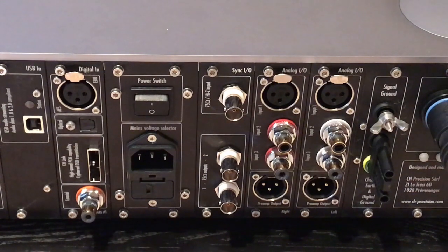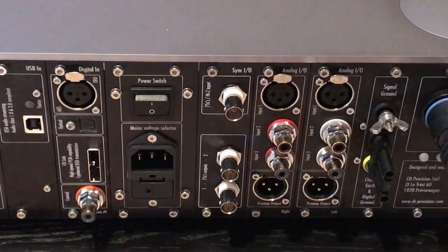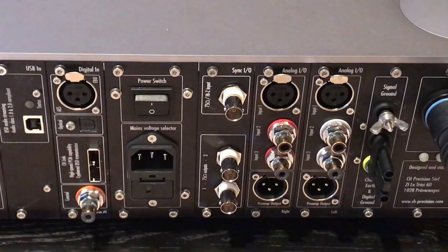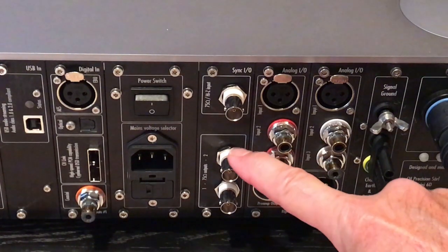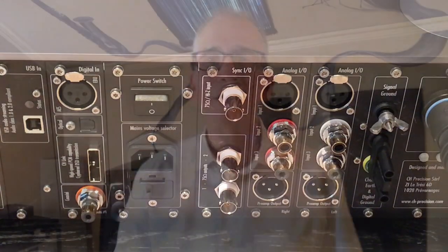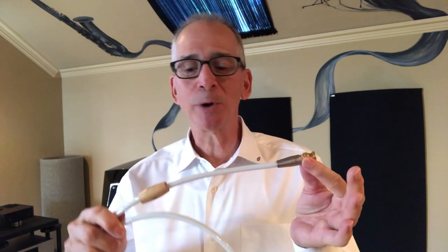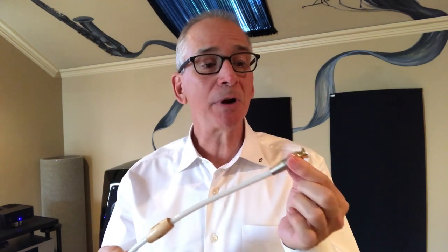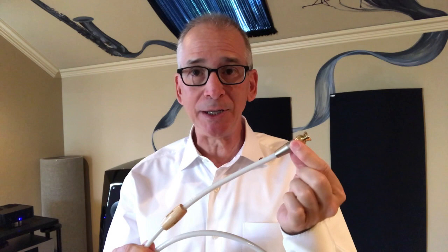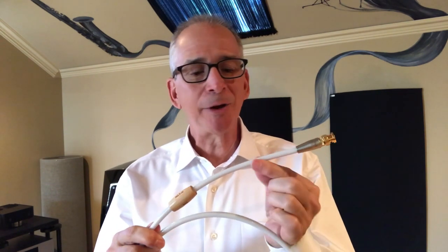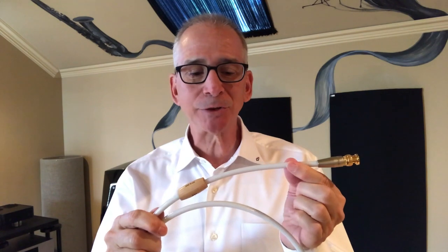Connect the clock cable to the topmost BNC connector, clock in, of the D1. Then connect that cable to either of the clock outs on the C1. Clock cables are an integral part of the digital clocking subsystem, so using well-made, well-designed cables is essential if you're going to get the best results. I use Nordost Valhalla 2. These cables are terminated with BNC connectors that we need for our clock sync cards, and they're meticulously designed and manufactured to the required 75 ohm impedance.